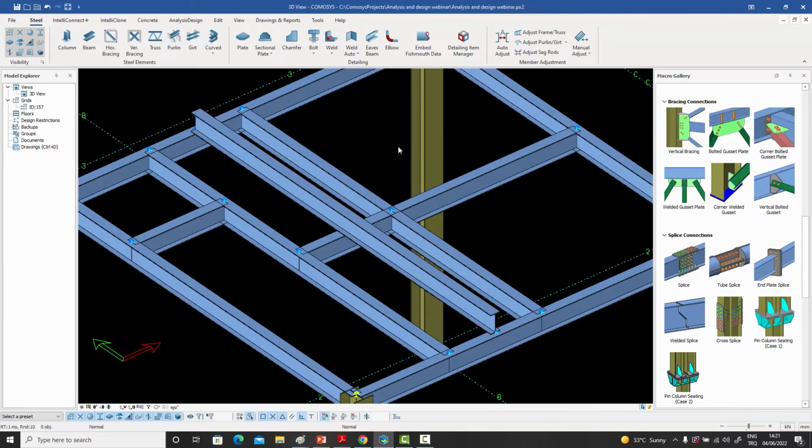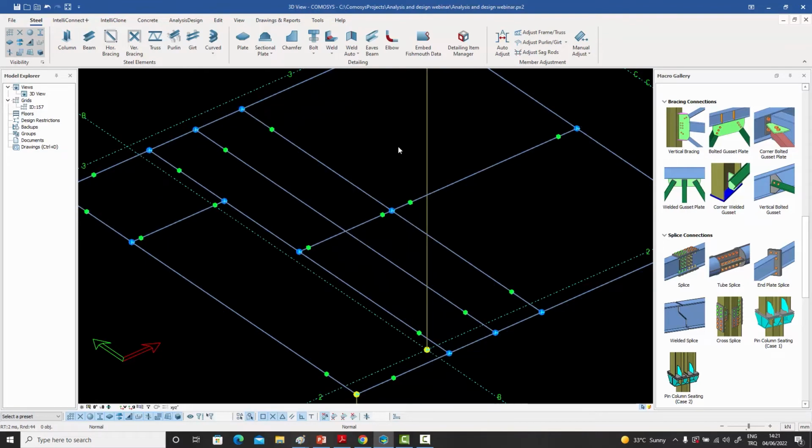And if I were to go to my finite element model, which I can do by pressing Alt D a couple of times, I can see the line mode. You can see that this line is continuous as well as this line is continuous, but no node is formed over there because right now they're oblivious to the existence of each other. This one doesn't know this one is crossing over it, because only one member can be continuous.